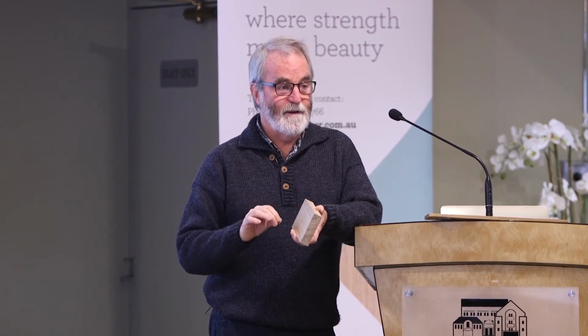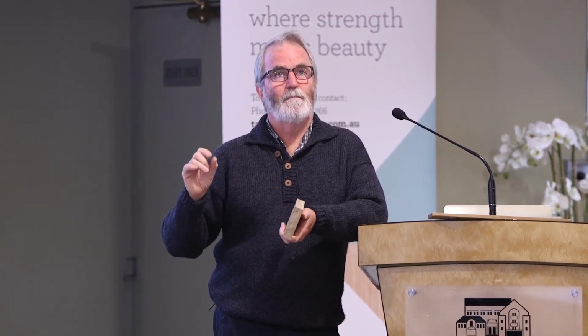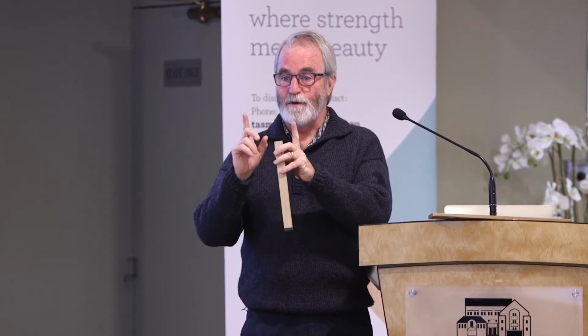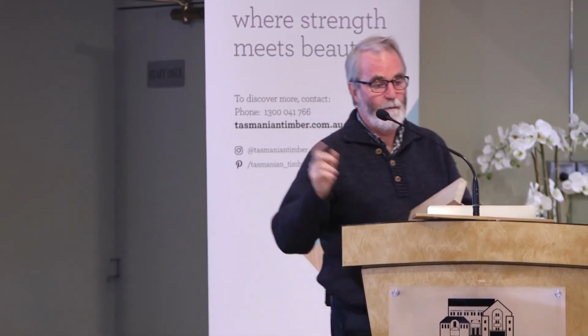Because if I don't, and it starts to grow, because it works both ways, shrink and get bigger, if it starts to grow and it's growing at 0.03% for every 1% change in moisture content, and I've got a 50-metre run of board, then I'm actually adding up to a pretty big movement, which I want to make sure I've allowed for. So that's why